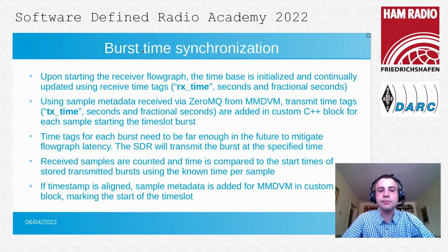Using the sample metadata received via 0MQ from MMDVM, we also add transmit time tags inside the custom C++ block for each sample which is starting the time slot burst. This is necessary in order to tell the software-defined radio transceiver at which precise time in the future it should start the transmission of the burst.